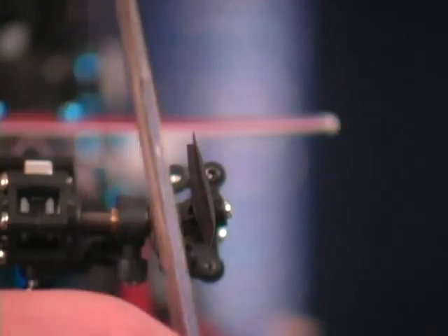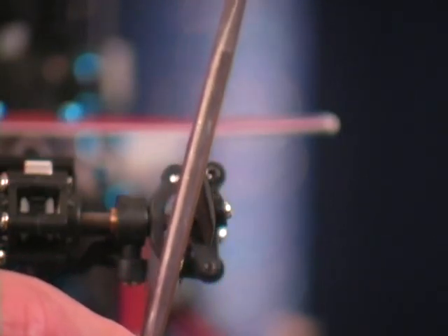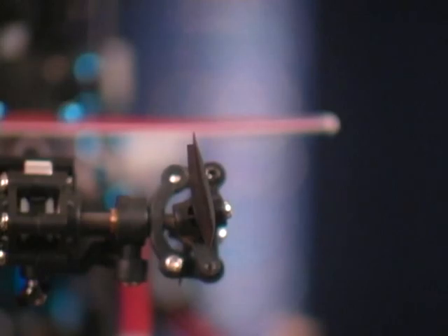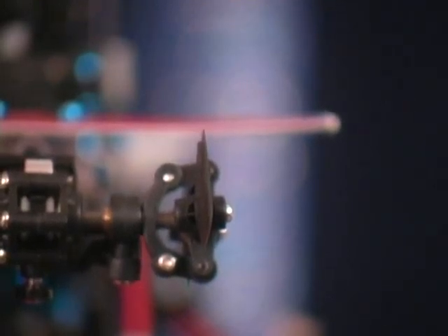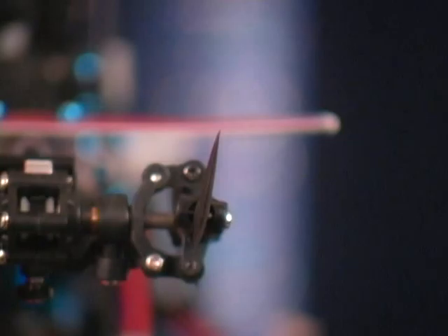Now you can see that the tail rotor is angled like this. What we want to do is change the tail rotor so it's angled about like this, and we do that simply by taking two pliers and putting one on either side of the tail rotor push rod, and then just shortening the tail rotor push rod so that we have something like that. That's going to be close. Again, we'll fine-tune this when we lift off the helicopter and hover with the gyro in the rate mode.